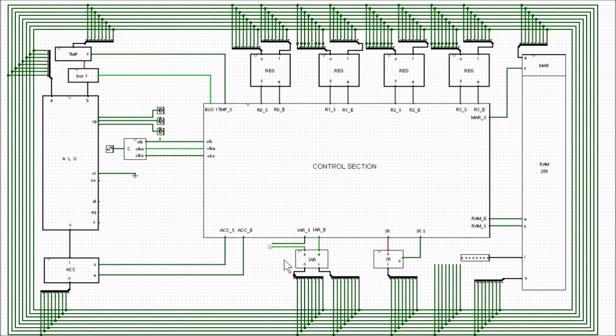Now secondly, you'll see that I've nobbled this as well, and I've changed the set here to high. The reason we're doing this is that at the moment we don't have any reset functions within any of these registers, so in order to get the initial conditions correct for the moment, I'm just having to put the set to a value of high. Okay, so that's just an initial condition, and whenever we work our way up the hierarchy, a reset function will be provided.